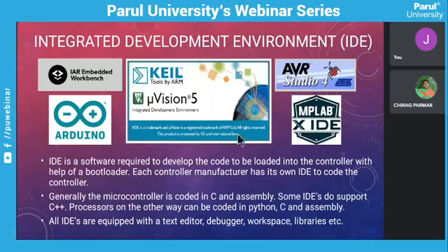Okay, the main advantage of using these IDEs is that it uses pure C. If a blink program in Arduino is used, it just blinks an LED, and the storage space of that program might be a KB. Out of 32 KB, it uses almost 1 KB. But if the same program is written in pure C in any of these IDEs, it won't take more than 200 bytes. So the program size reduces to almost 1/5 of the program size required in Arduino. And that's the main advantage of it.